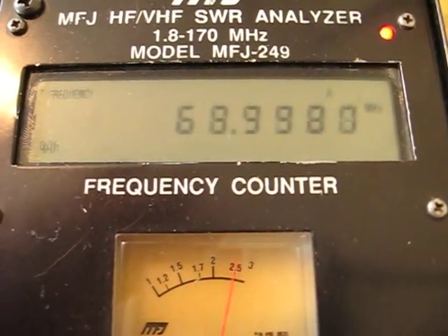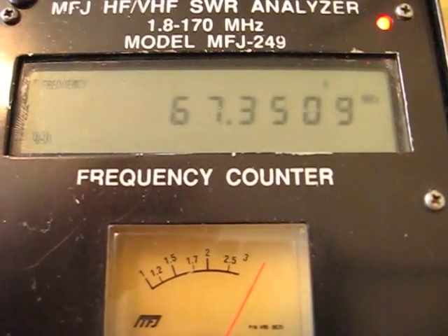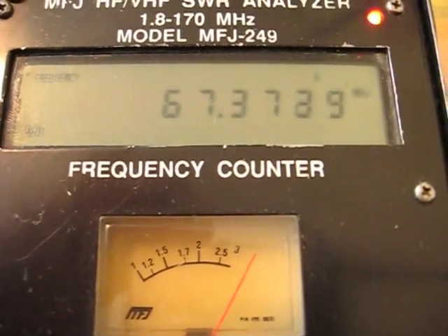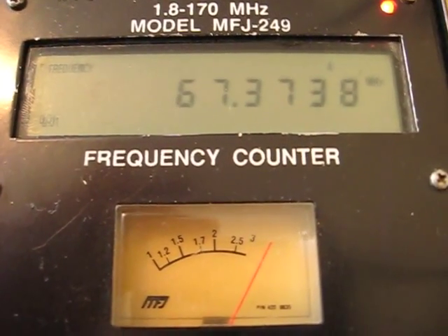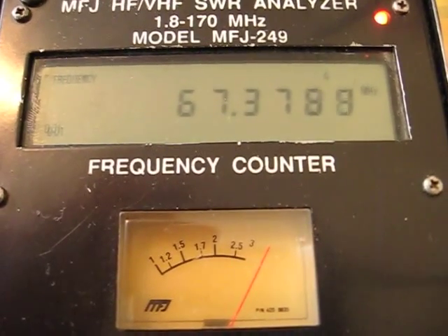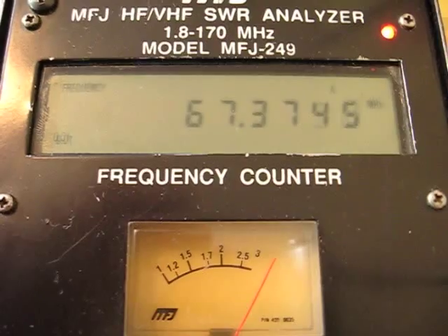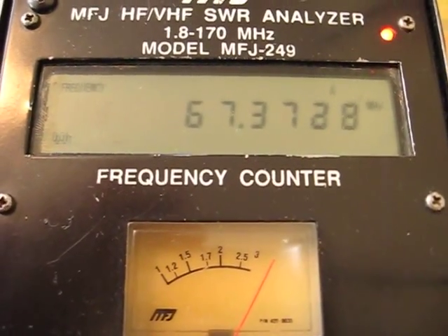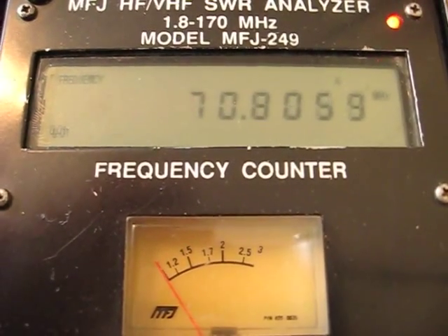But if the multiples of half a wave were, say, at this frequency, then it would require snipping from the other end. Small snips at a time. You can get a little bit excited and think, oh, I'll take 2 inches off this time, and then it's just too much. Waste of coax, throw it away, or use it on another frequency.